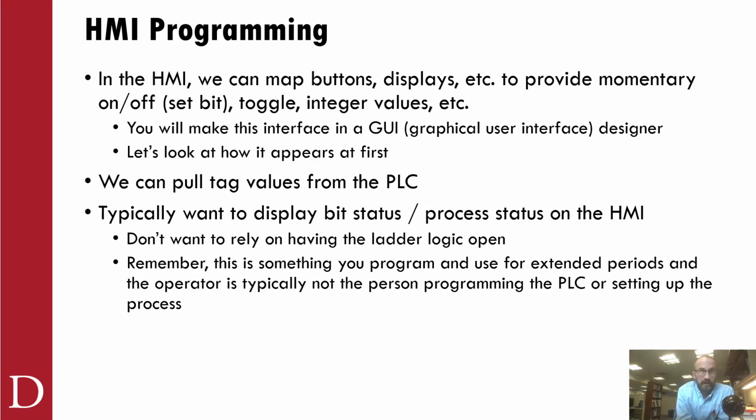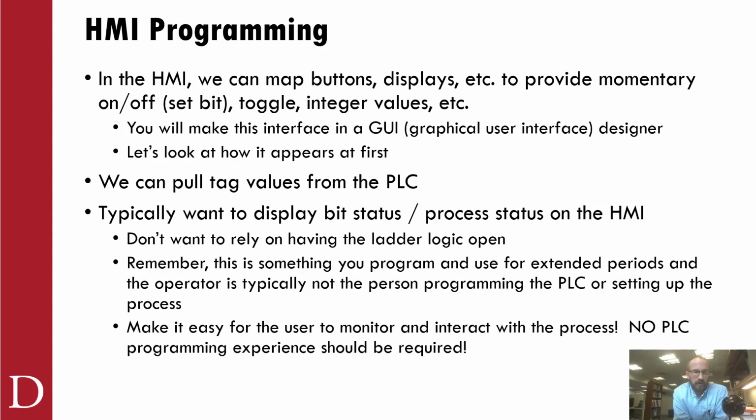And one thing to keep in mind as we're working with HMIs is this is for the user of that piece of equipment, so they shouldn't necessarily need to be the person programming the PLC or knowing how to program a PLC, but they should be able to interact with the PLC and change anything that they need to do the operations using the HMI and PLC program. So you want to make it as easy as possible for that person, right? They should be able to have it fairly intuitive, know where buttons are, know how to change inputs or outputs, and work from there.